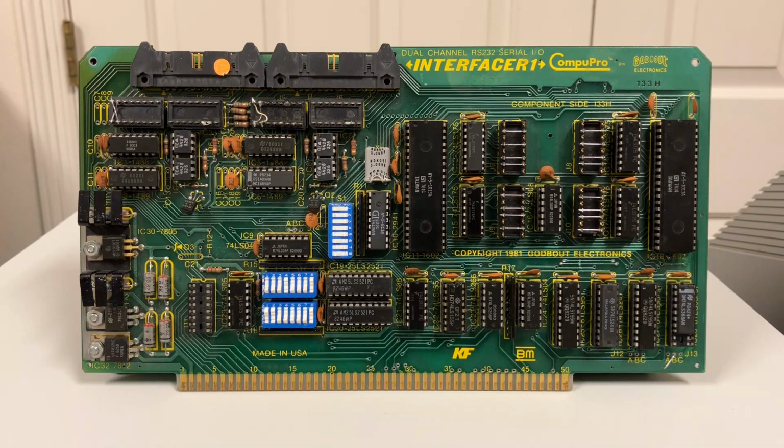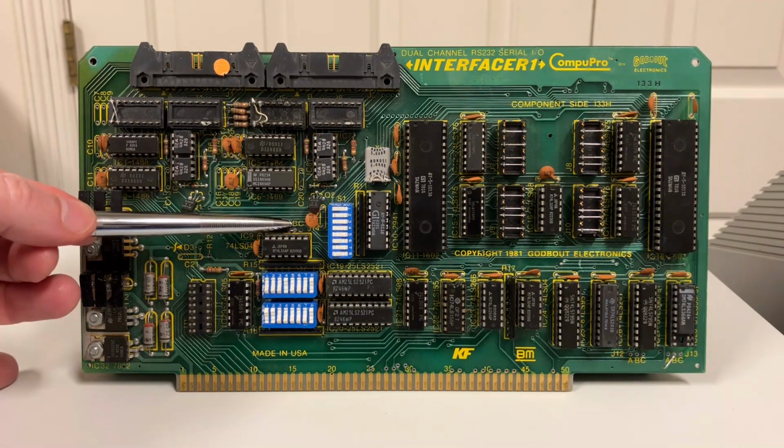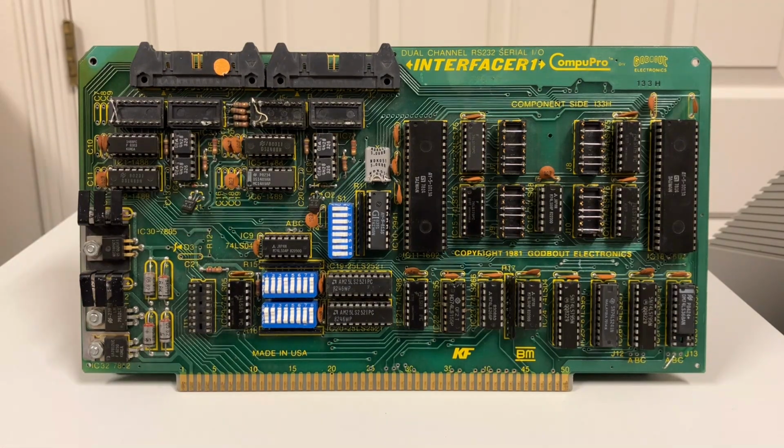And then the next thing we want is we want status at 6, data at 7, as opposed to the other way around. That's done with this ABC jumper here. We've connected A to B. That gives us status first and data second. In the B to C position, you get the opposite. And B to C is a default on this board. There is a trace in there to begin with. So if you really want to use this ABC jumper, you have to cut that trace first, and then you can wire either way you want, or install a 3-pin header and use a jumper.